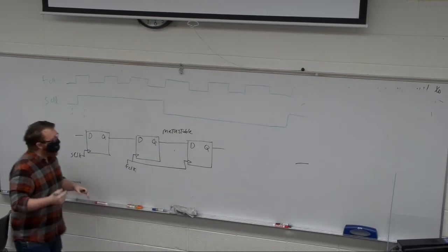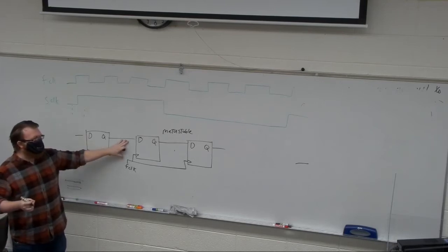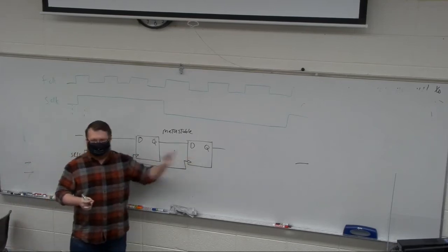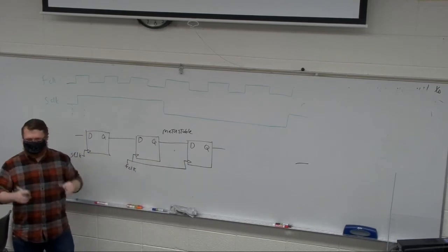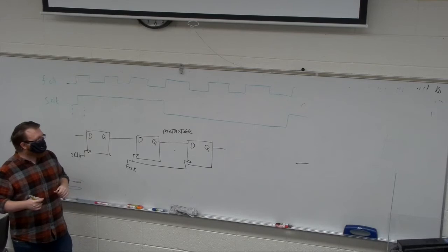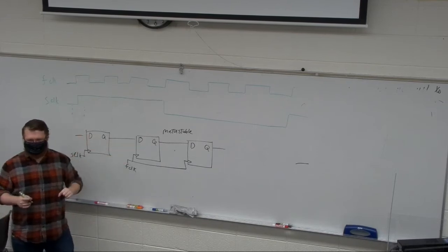They're synchronous. So all that we have to do, we talked about the same idea for debouncing, and 2 flip-flops is enough. And all that means is we have to wait for one fast clock delay, one extra fast clock delay, instead of just plugging one into the other. Done, we're done. So like I said, slow to fast is fairly easy.